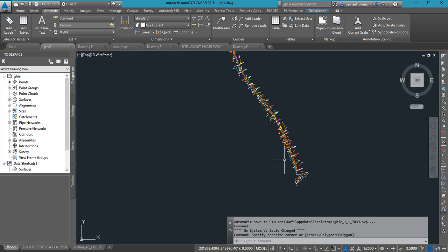So somebody should give us a typical road cross section in terms of the width. Carriageway width. What carriageway width are we using? Okay, so the carriageway will be 7.3. Then, are we going to have shoulders or walkway? What's the width? Let's say a shoulder of 2.5. So we have 5 plus 7.3. That is what? Is it 12.3?